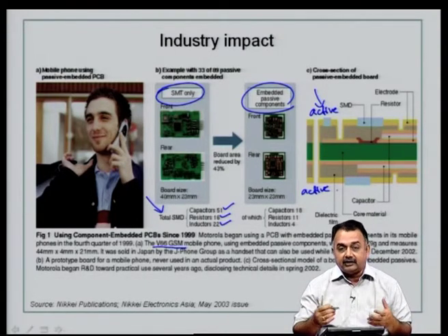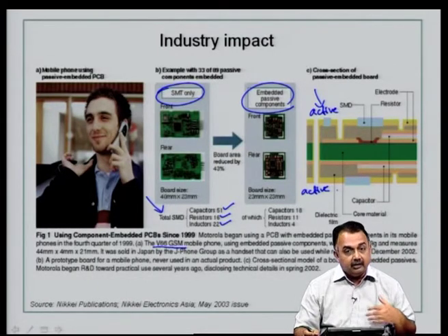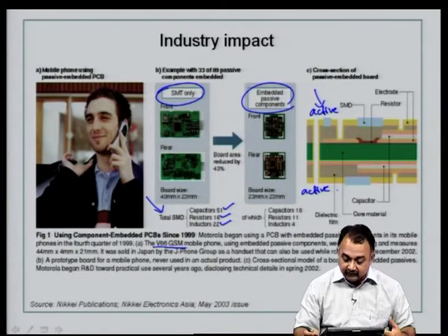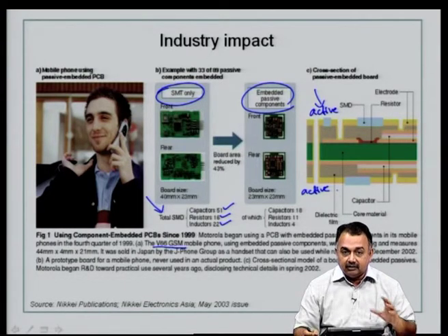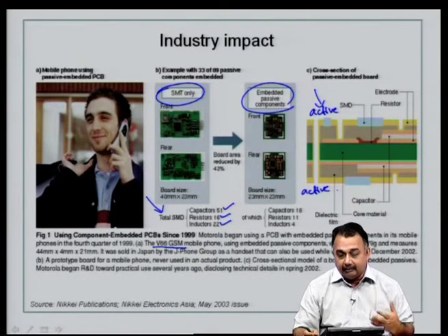You also have the flexibility to choose different dielectric materials for your capacitor, and in fact, if you want to have 2 resistor layers, 2 capacitor layers independent of each other, but then connected to the main core, that can be designed as well. You can use different resistor materials and different capacitor materials with a set of properties that are suited for your application.